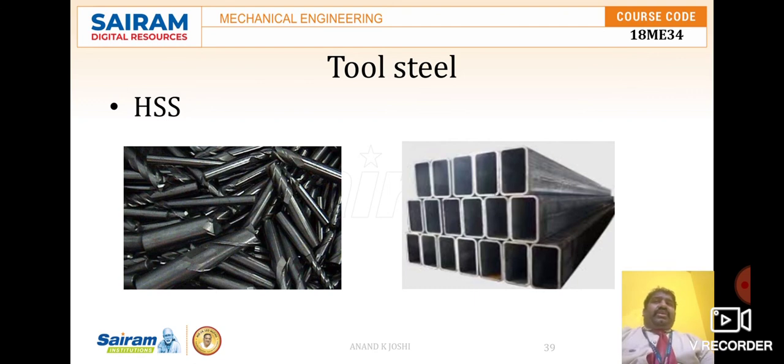And finally, some of the steel designations we are using. For example, the Society of Automotive Engineers and the American Iron and Steel Institute have established standards for specific analysis of steel. For example, if you take SAE 1040, the 1 indicates carbon steel, 0 indicates plain carbon steel, and 40 is the carbon content, that is 0.4% carbon. This is about the specification of that particular steel.